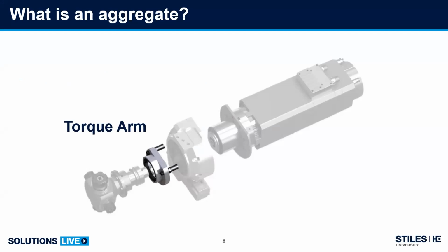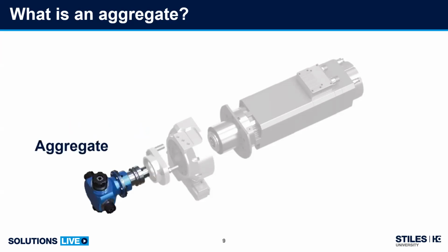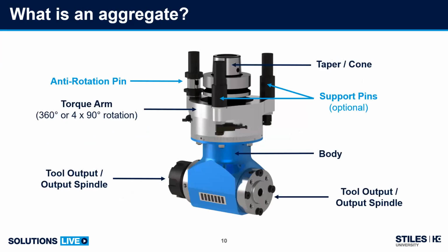Furthermore, components on the aggregate: we have a torque arm. Essentially these are anti-rotational pins that would fit up into that aggregate retention ring, or coupled with the C-axis as you see there. They stop the rotation so we don't have the entire aggregate body just spinning wildly. It forces the rotation to be only through that machine connection. That's how we power the aggregate without it spinning out of control. And then down to the aggregate body itself. We'll take a deeper look at that aggregate body here.